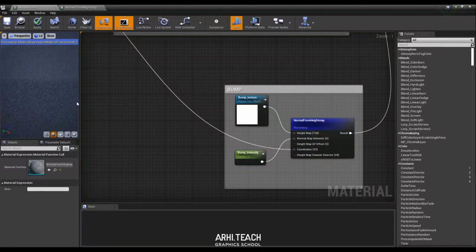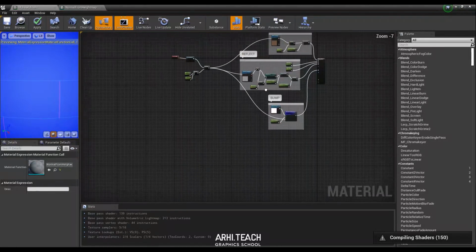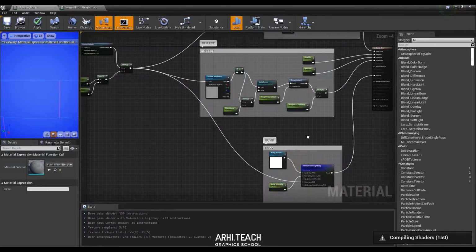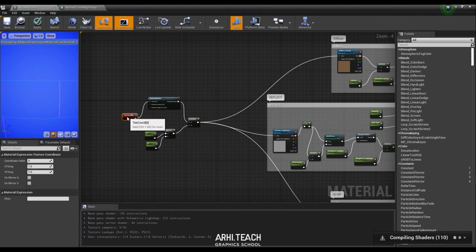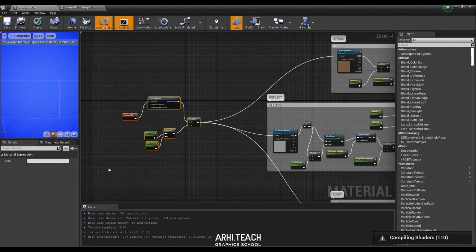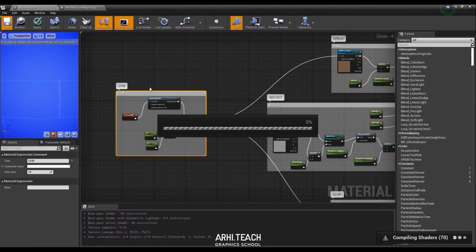I am saving this now, and you will see then, because we had a shift here, but now we have an exact normal bump. That's it, we decided on this. So we have bump, we have reflect, we have diffuse, and we also have control over these textures. I select the U/V branch and then press C and sign that we have UVW. I'm saving this material now. Next, from the base parent, that is, the parent material, we need to create an instance. It's important to save the structure I showed just the way I showed it.